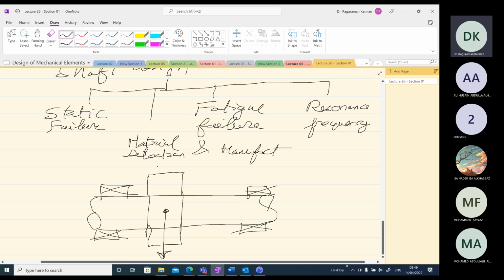So this gives us a bending moment. You consider any point A at a particular time, where is the neutral axis? Right in the centroid here. So at one moment you have the maximum compressive load here. The same point comes down here after some time and it leads to the tensile load over here. But since we have a circular cross section here, whether the point is on the top or the bottom, we have the same magnitude of stress.